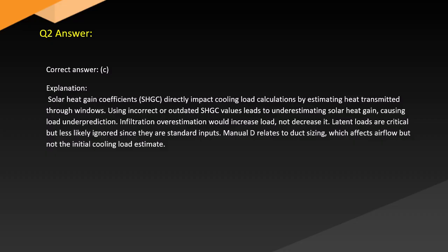Infiltration overestimation would increase load, not decrease it. Latent loads are critical but less likely ignored since they are standard inputs. Manual D relates to duct sizing, which affects airflow but not the initial cooling load estimate.